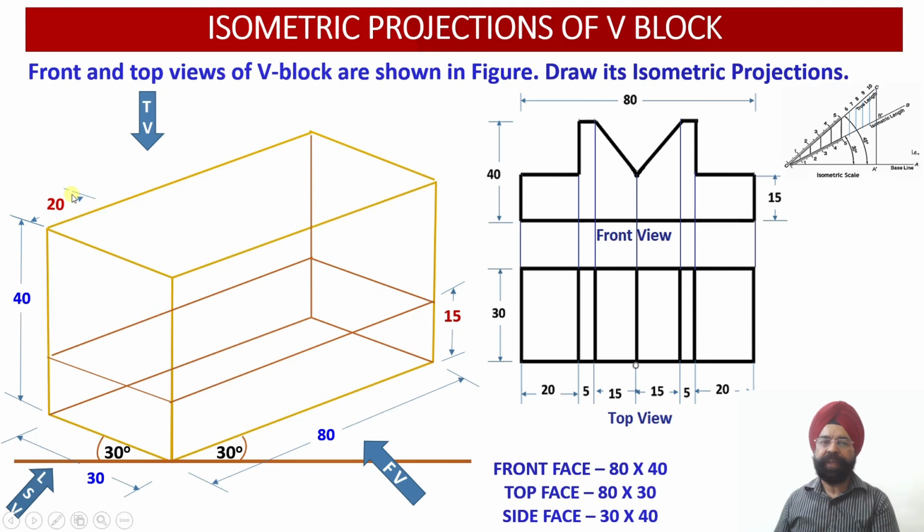Now I have left 20 millimeter from the left corner, and from here, please check, I have drawn a vertical web. How did I draw this vertical web? This is my 20 millimeter distance, which corresponds to this portion. So I am moving from here. As I move along up to this point, from left to right, now I have to move vertically downwards. How much? 25 millimeter. That is up to this ring over here. This ring has a thickness of 15 millimeter.